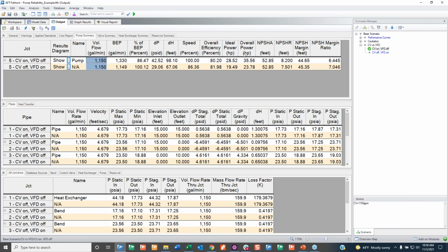So we will look at overall power, which accounts for efficiency. So again, when you're using a control valve, you're adding a whole bunch of power to your fluid. And then you have to take it away with that control valve. That's what that little pressure drop dotted line I was showing was on the slideshow. Well, if you just collapse your curve to begin with, you're using way less power.